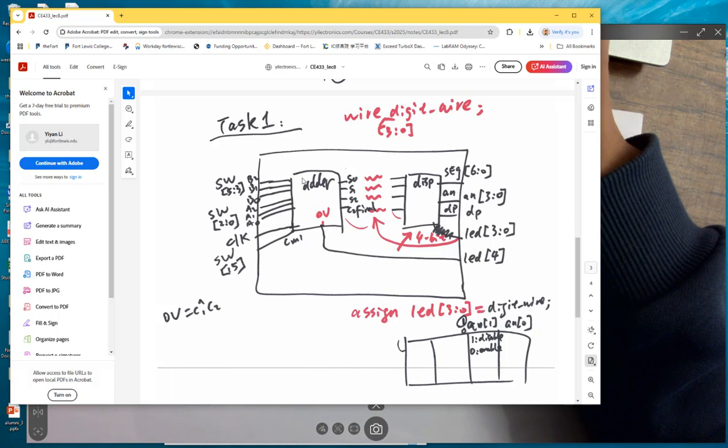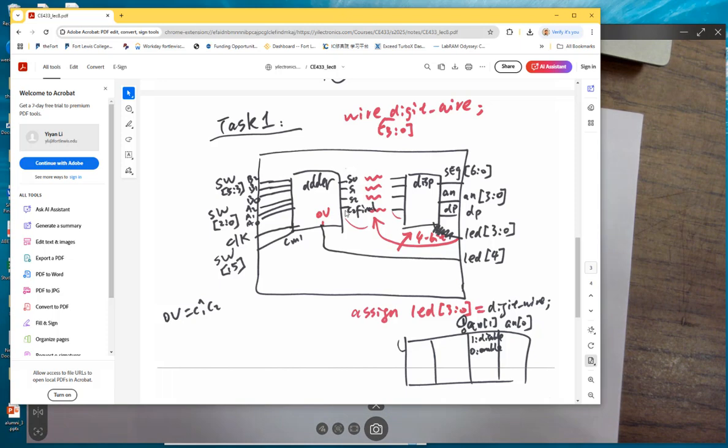And eventually, the adder is in charge of delivering the 4 final results, the 4 bits. Okay? So now we have the final results, the 4 bits. But the problem is the final result is in 2's complement. That is why we need a sort of lookup table. The case, right? All different cases. If you see this case of the 4 bits, you want to display what?